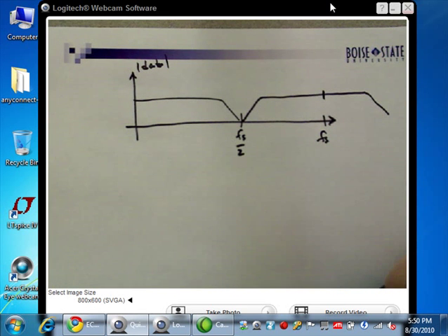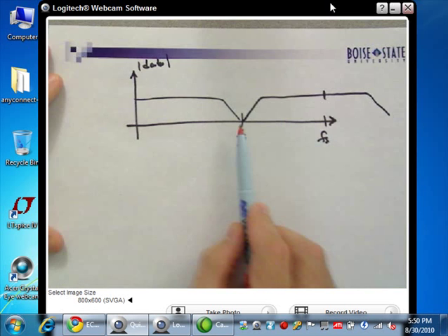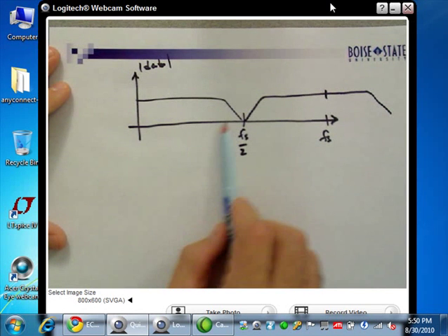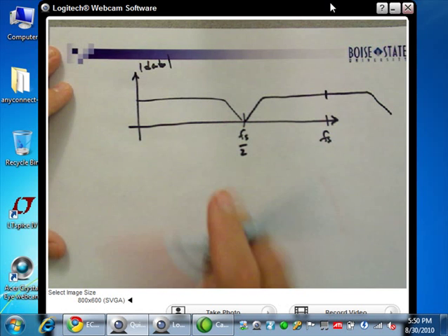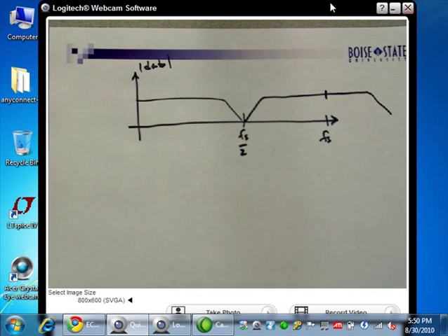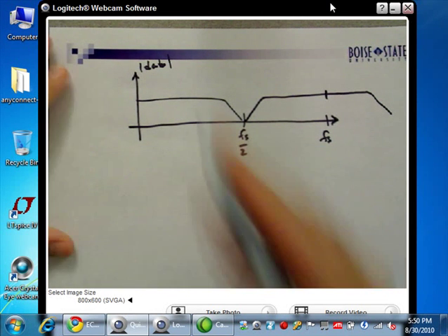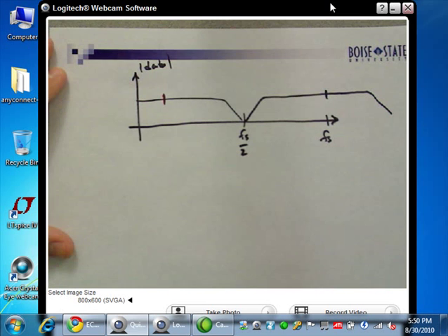Now if I'm going to decimate, it's just like the analog way. I can't decimate if I want data out here because then it'll alias. So I have to have some limitation on my data, right? So I might want to say only this amount of data here. A great example of decimation is compact disc players or MP3 files. They encode or decimate with a really good sharp cutoff filter, and that's how they are able to store less data, right? But that's decimation right there.